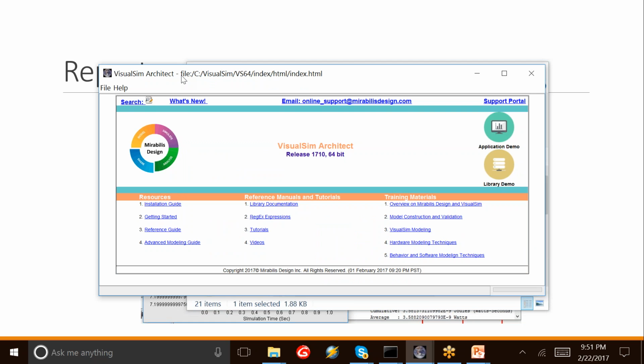So for example, say you have a Bluetooth device. You can look at what happens when I do a broad advertise versus a narrow advertise. What happens when I do a transmit versus receive? What happens when I go from sleep to advertise? What is the change in power? You can look at those.